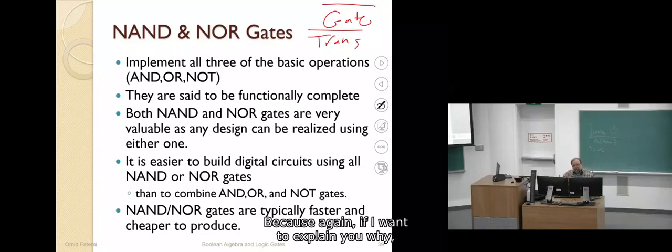Again, to explain why, I have to show you the transistor level of NAND and AND. In NAND, from the input to reach the output, we pass 1 transistor, but in AND, we pass 2 transistors. So it has 2 level delays, but NAND has 1, so NAND is faster.